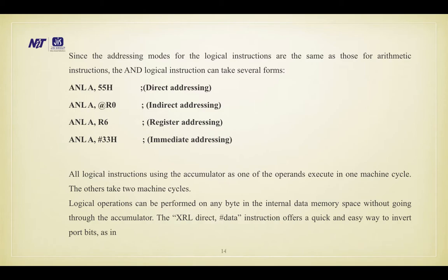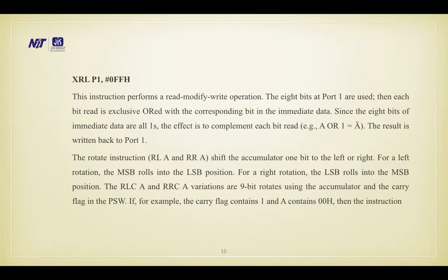Logical operations can be performed on any byte in the internal data memory space without going through the accumulator. The XRL direct, #data instruction offers a quick and easy way to invert ports, as in XRL P1, #0FFH. This instruction performs a read, modify, write operation.